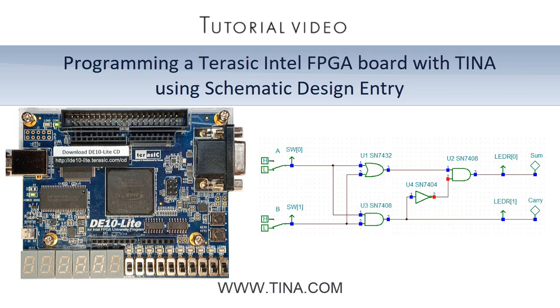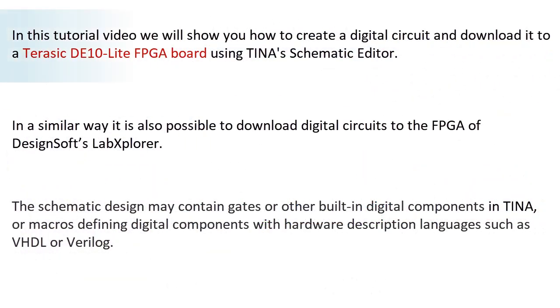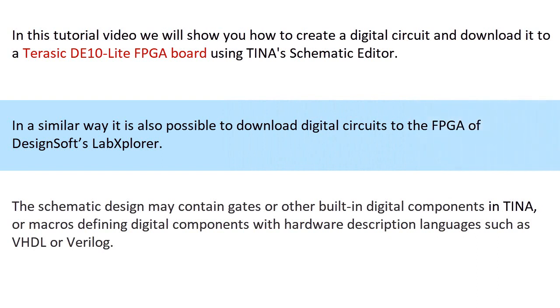Programming a Terasic Intel FPGA board with TINA, using schematic design entry. In this tutorial video, we will show you how to create a digital circuit and download it to a Terasic DE10-Lite FPGA board, using TINA's schematic editor. In a similar way, it's also possible to download digital circuits to the FPGA of DesignSoft's Lab Explorer.